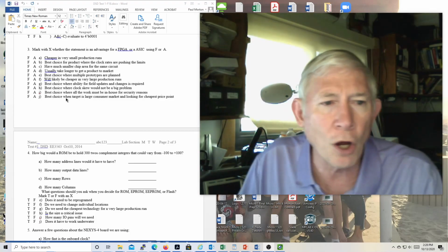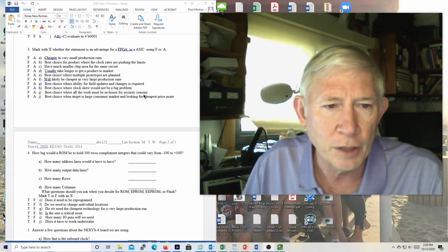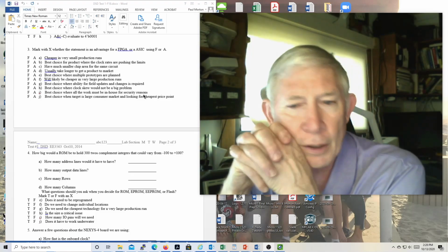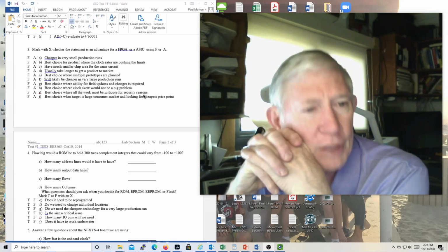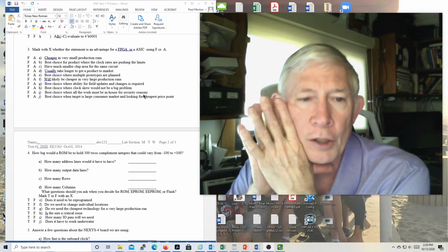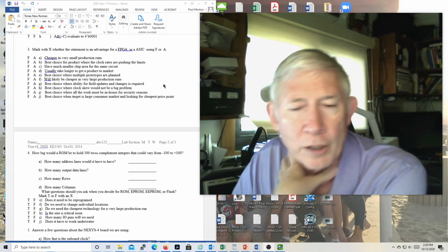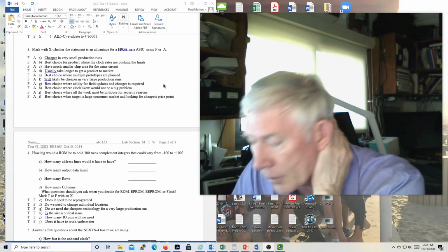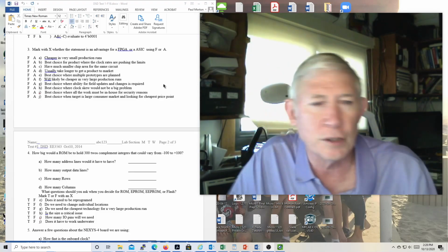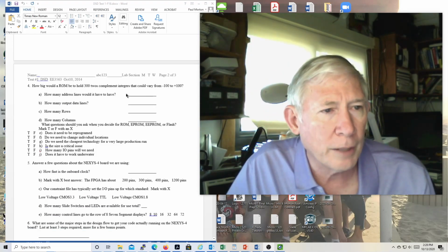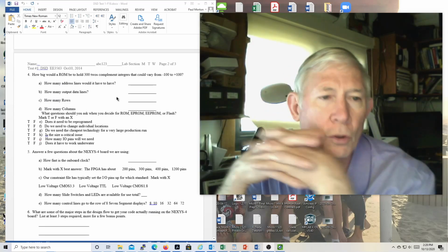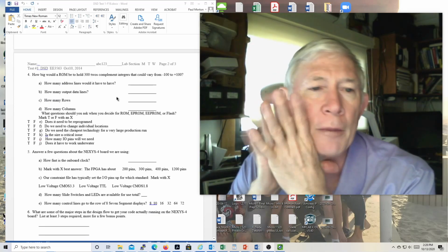Best choice where all the work must be in-house for security reasons. Yeah, if you're going to do that, then an FPGA would be nice. Best choice where the target is a large consumer market looking for the cheapest price point. Okay, so now if you're going to sell lots and lots of them, you're going to go with a dedicated chip.